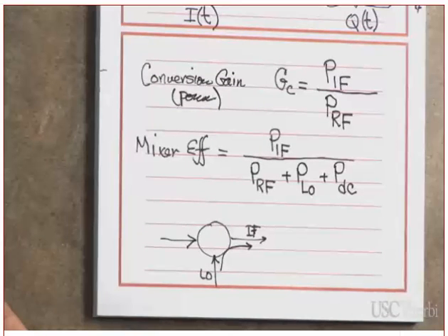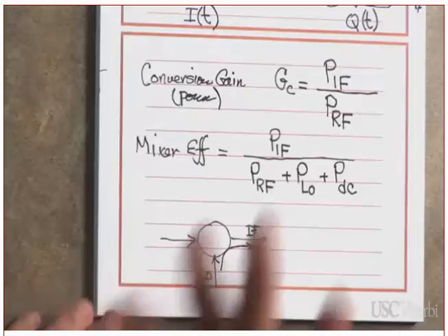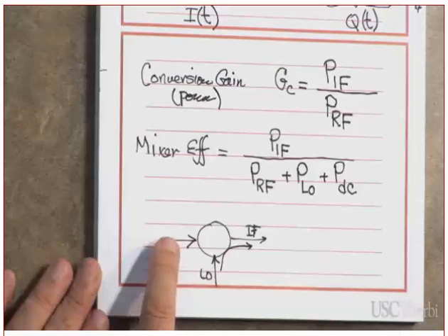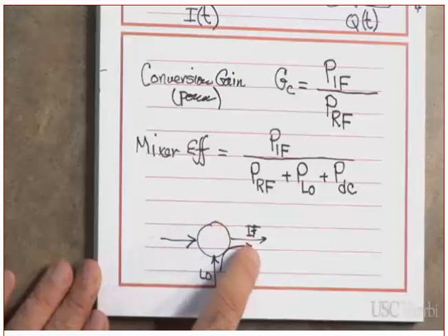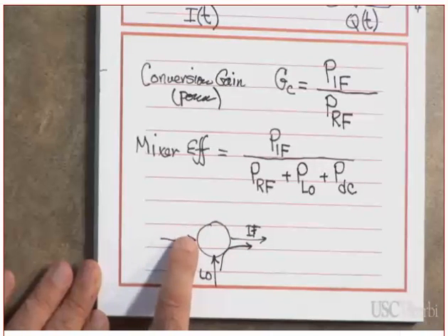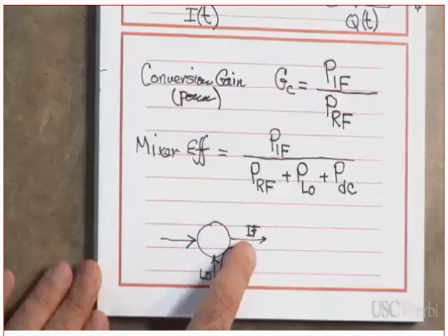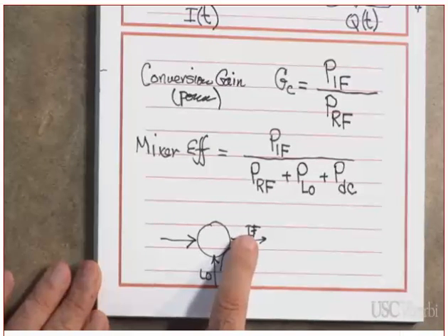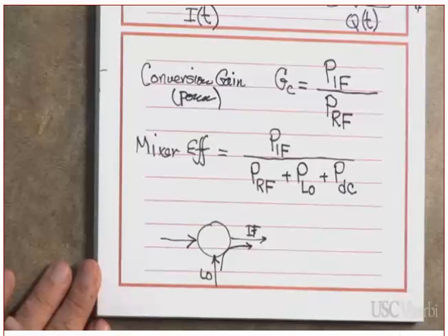Did you get my point? Now, if both of them show up, we call it an unbalanced mixer. This is an unbalanced mixer, and this is terrible. Did you get my point or not? Yes or no? Okay. Now, keep in mind, if the RF signal leaked into the output, then there is a possibility that there are some nearby components, near to the desired signal, and both of them leak in here, generating an intermodulation component, generating a signal which is close to the DC.